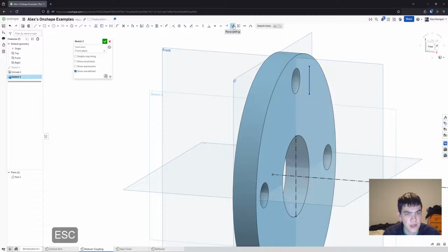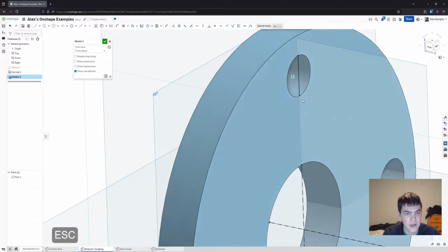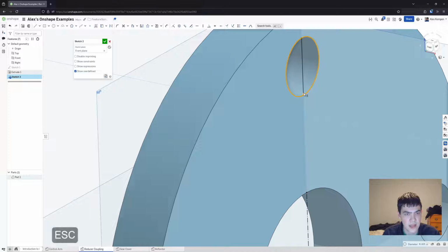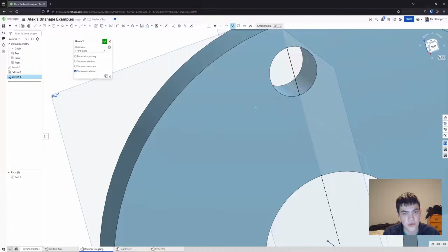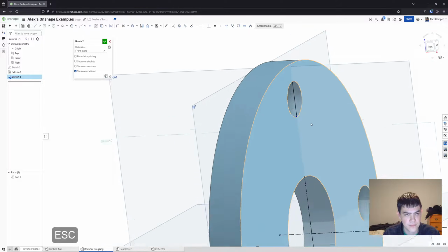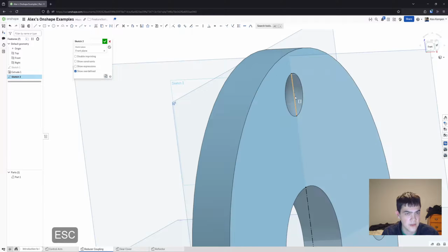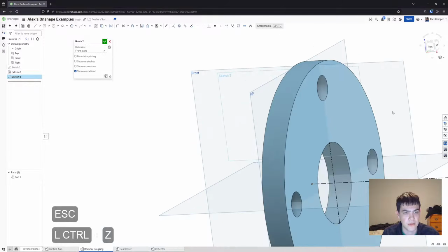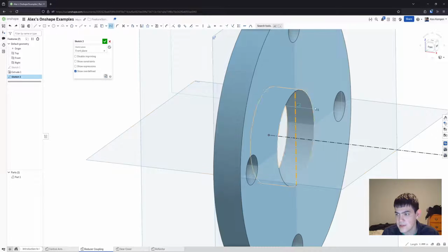And so, obviously, an alternative is to just create the entity manually and then add it yourself. So here I would have to use actually the Pierce constraint, which is one of the more esoteric ones. But that basically computes the intersection of the entity and the sketch. So you can kind of think of it as a coincident, except it's for stuff that's passing through the sketch. So I could add it like this manually, right? And this is of course equivalent to using this edge directly, right? So two alternatives. Doesn't really matter either way. But yes, that's how we get this line, right?